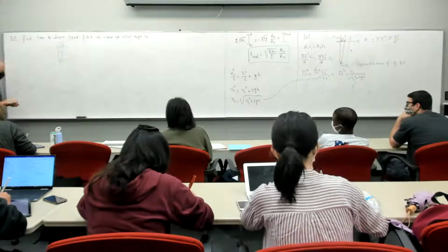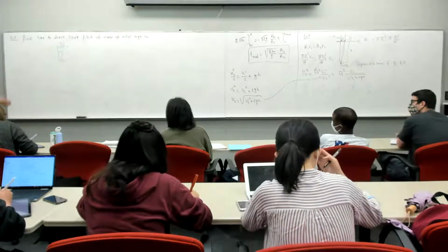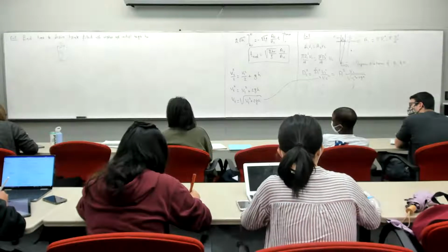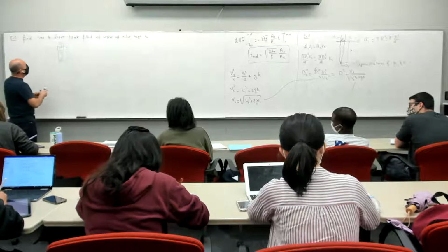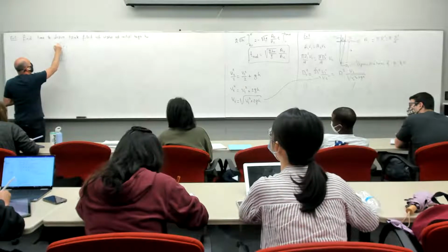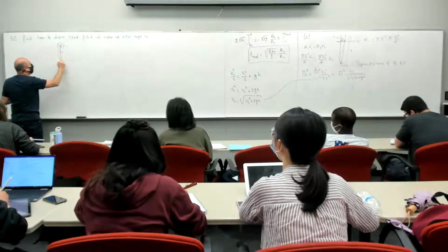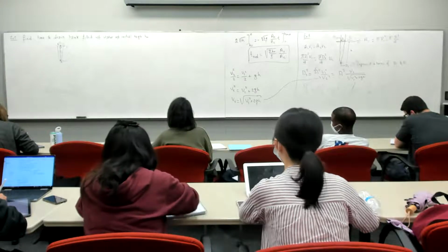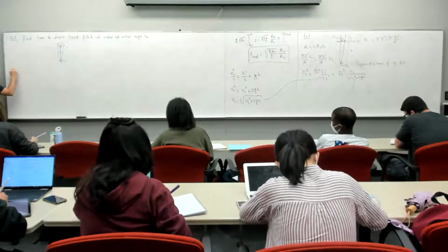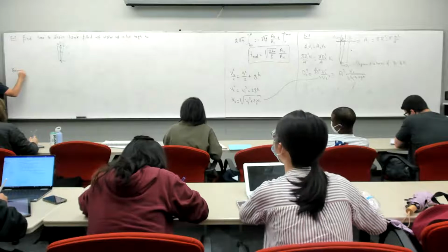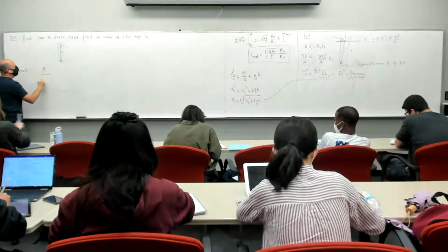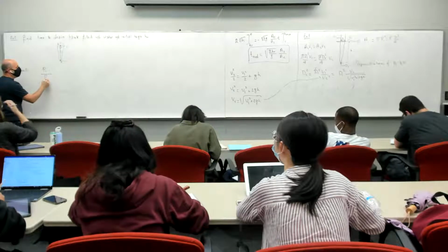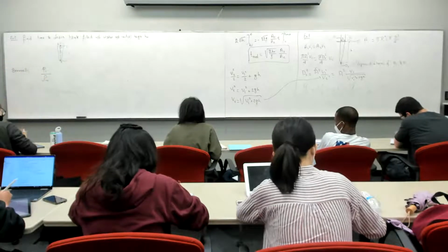we need momentum. Okay. So again, we consider that the flow is steady, inviscid, with nice streamlined structures, and we consider a streamline from point 1 to point 2 over here. And we write the Bernoulli equation. That's P1 over rho water, because we are in water, correct?